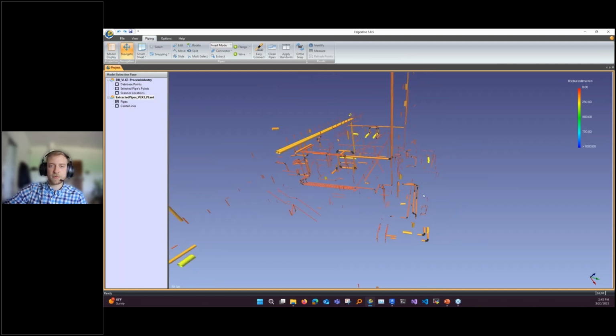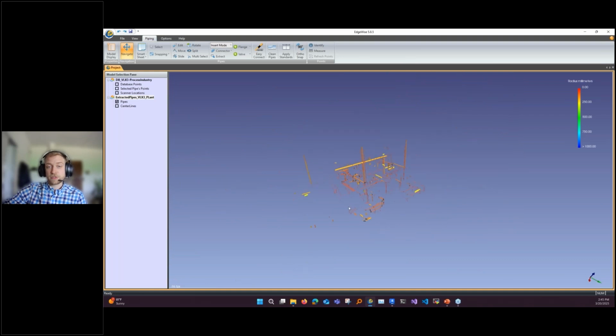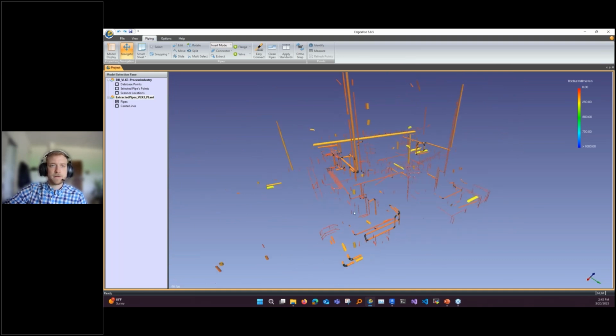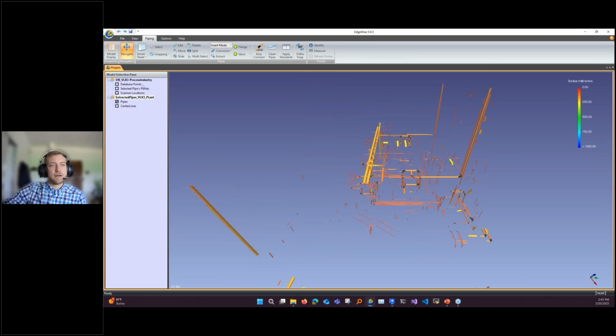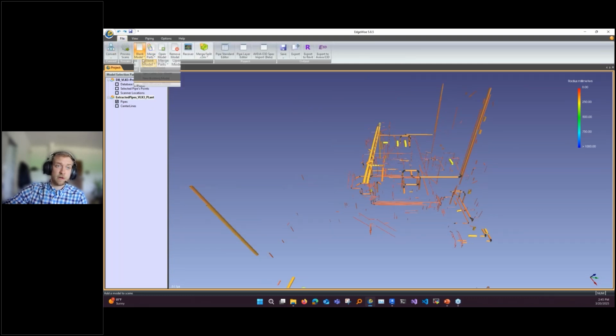For the sake of time, we're going to jump into the structure side of things, because there's a lot of other pieces we want to go through. For structure, cable trays, and ducting, the way to make a structure model is to go to the blank model section and create a new structure model. That's true for ducting and cable trays. If you want to create that geometry, you need to start by making a new empty file and then work through that.